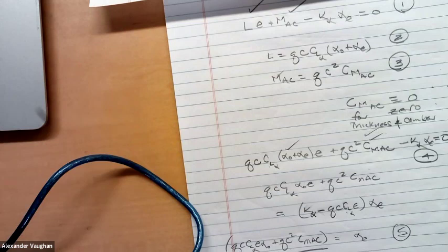But what really causes alpha E to get really big is when the denominator vanishes, which will happen when this aerodynamic factor overwhelms the stiffness of the spring, we're getting a very large deflection. And it's when the denominator is 0 that we call that divergence. So divergence occurs.